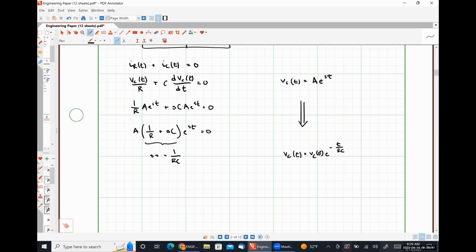So we see that capacitors obey an exponential decay wave shape very similarly to inductors, except that for the RC circuit, the rate of decay is determined by the resistance and the capacitance. So these two things are incredibly similar to each other, and electrical engineers are lazy and don't care whether or not we're using a capacitor or an inductor as an energy storage element.